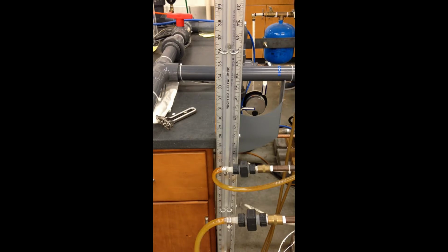You will also note that as I increase the flow, two things happen with the manometers. One, of course, is that both manometers begin to rise as the pressure increases, but also the difference between the two likewise increases, which you would expect from the theory I presented earlier. This is orifice number 2, and we're going to take it all the way up to full capacity. You can see that the difference increases as the flow increases.